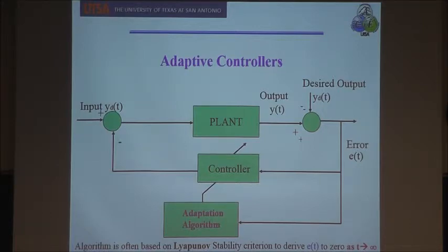The idea is the following. When you have a physical system, but for your design purpose you're representing it by a mathematical model of it, as good as that model may be, it's not the real thing. So you put your controller, in this case this controller I'm showing to you, which is based on the mathematical model of this plant, and you close the loop, and for most of the time you may be okay, be happy.